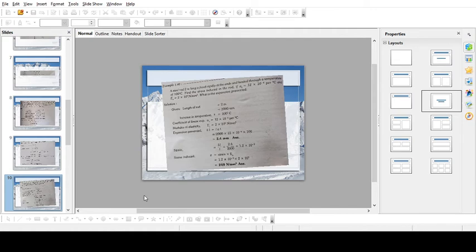Sorry, that is sigma S AS equal to sigma C AC. A mistake is given in the printing. So stress into area should be equal, nothing but load. So the stress of the steel is equal to 2 by 3 of the stress of the copper.